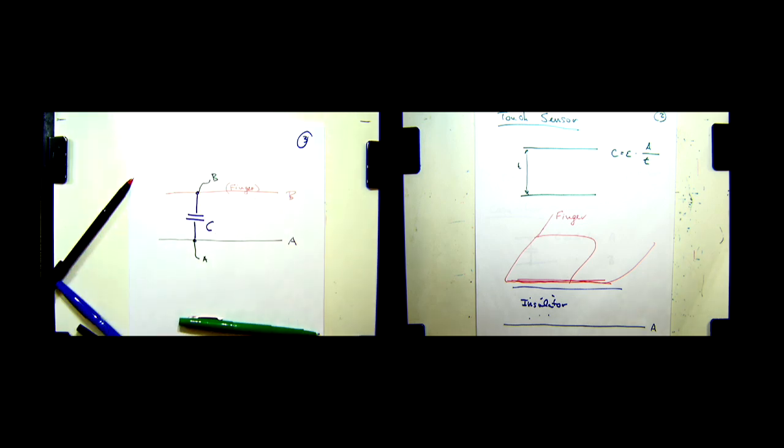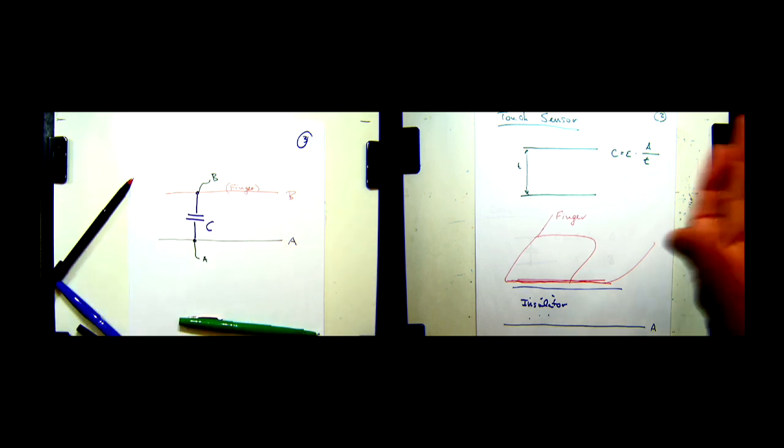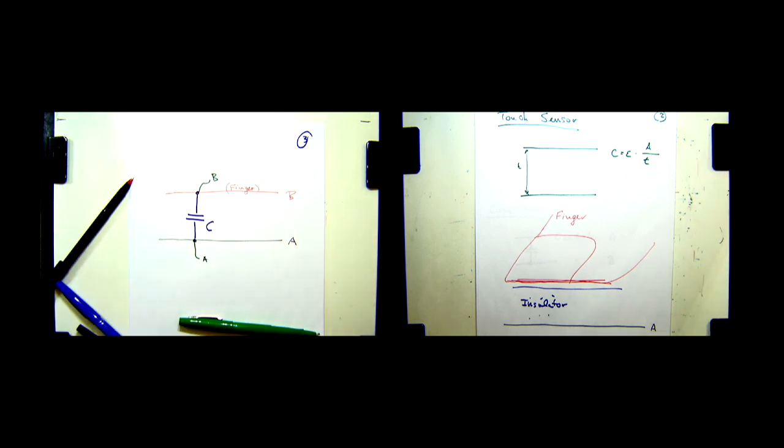Okay? And so we still need to figure out, once we have these wires there, what kind of an electrical circuit we're going to use in order to measure or detect the presence of this capacitance. But, I mean, let's just deal with the wires for the moment. Is it difficult to put the wire A? No, we have a plate there, it's conductive, we can solder it to it, or clamp it to it, or glue it to it, whatever. Use conductive glue. What about the wire that goes to B?